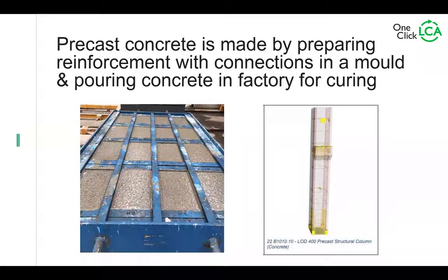Right, no, I forgot to say one thing. So the precast concrete also does provide you the opportunity to optimize it with, for example, hollow cores, which is a very effective way to reduce building mass for slabs. Or as somebody mentioned, bubble deck. So you can substitute cement much more efficiently in a precast environment than you can in a ready mix.